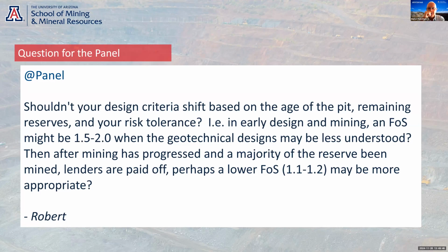But one interesting reflection recently on some projects was dumps and dump design. They may have been designed to a certain factor of safety, but at closure, environmental considerations require a higher factor of safety. It's very difficult when you've designed a dump to a 1.3 factor of safety, but at closure it needs to meet 1.5. There's no magical number you can give to add a certain proportion of design acceptance back into your design. So I guess key there is know what your requirements are in terms of your corporate factors of safety or design acceptance criteria, because those are the ones at the end of the day, and even at closure, you'll need to conform to.